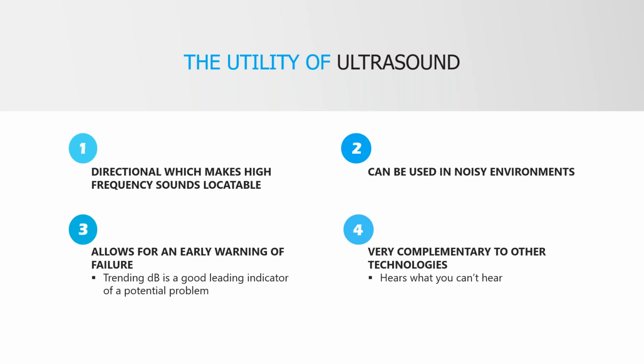Now, in some cases, there are sources of competing sound or competing ultrasound, so we just have to be conscious of those. But because high frequency sound is very directional, meaning that it doesn't travel far from the source, it makes it very easy to locate the sources of these different sounds within a typical plant or facility. And we'll talk about a way that we can use to actually pinpoint where that sound is coming from.